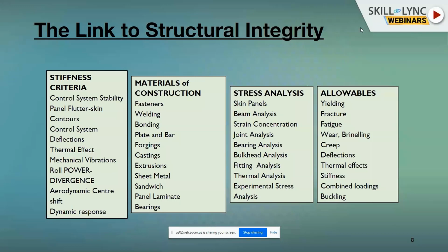If a panel is not going to go through any bending load, then it's not good to design it for bending. If a panel is not going to go through any torsion, then nobody wants you to put on extra weight. You can reduce the thickness, or change the profile of the cross-section. Then how many fasteners you need to install.